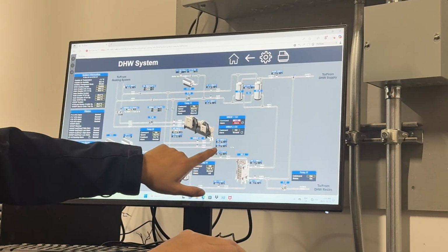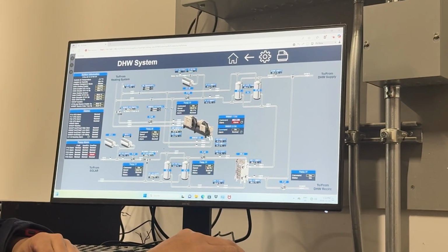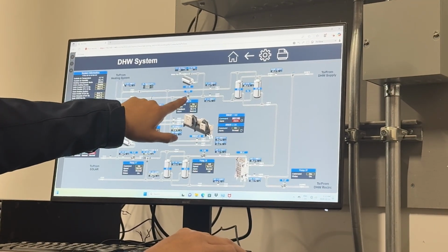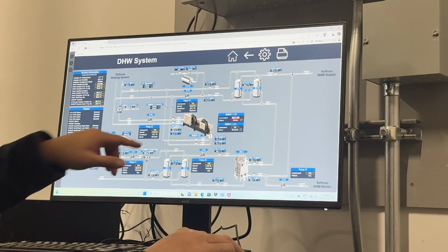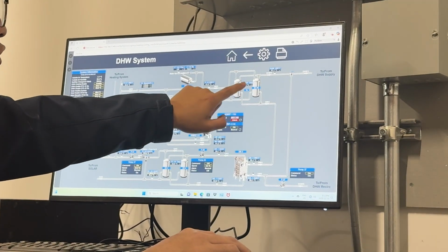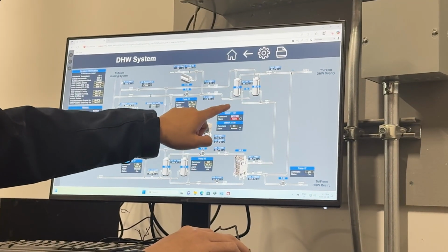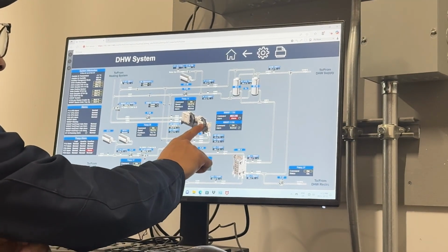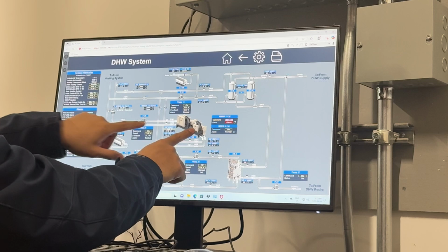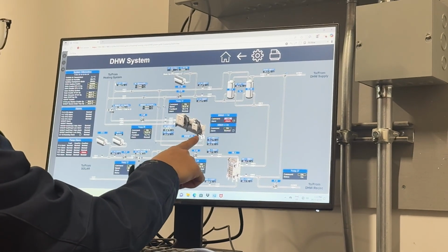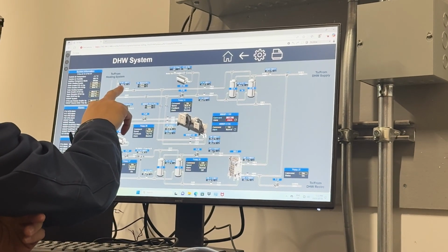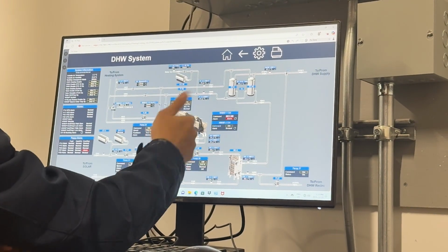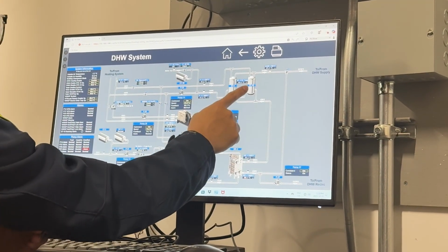So water-to-water heat pump supply water temperature is 61, right? It does the heat. The pump 14 is turned on. The heat is now dumped to storage tank 5 to 10, and then the water returns to the water-to-water heat pump. So the water-to-water heat pump, it's like boosting, right? Because the boiler loop temperature is only 53, 52. We want this to be at 60. So the water-to-water heat pump does the boosting up for the temperature.